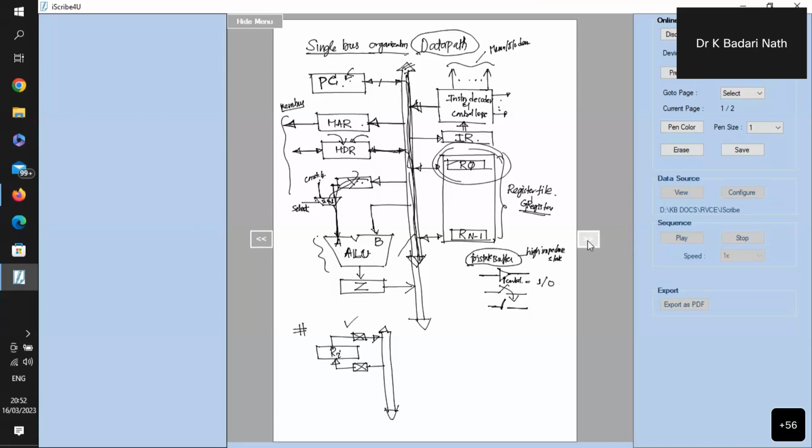That means some circuit, generally the instruction decoder circuit, should generate small control signals which make it open or close. Since it generates a number of signals, I'll call a name for the control signal, which is generated by the control unit inside the processor. So those names will be referring to the different buffers.